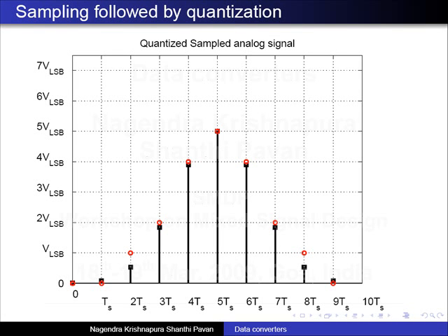Why will there be a sync? No, that's okay. See, I already know what happens to the sample signal. When I go from sample to quantization, what will happen to that? Okay, you're saying noise floor added. How do we know that noise floor is added and how much noise floor is added? But what is the quantization error? That's what we want to find out, right?